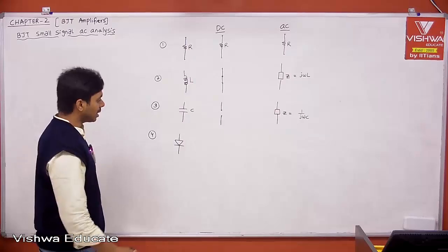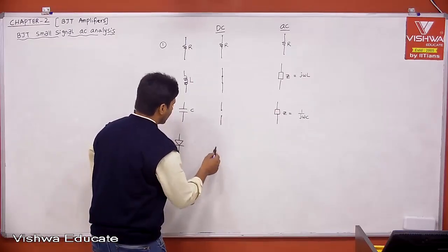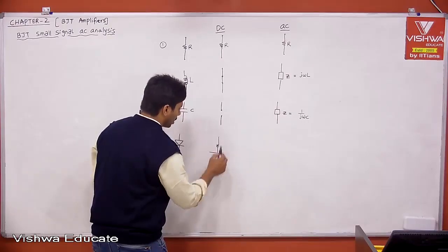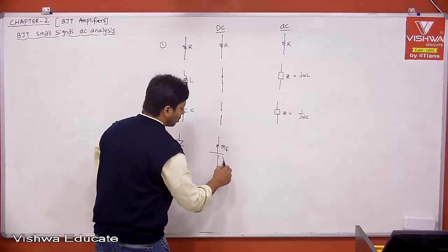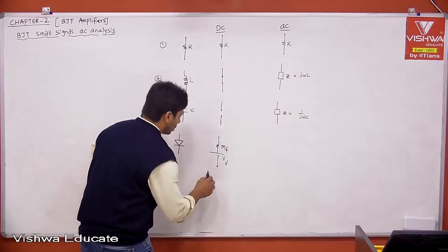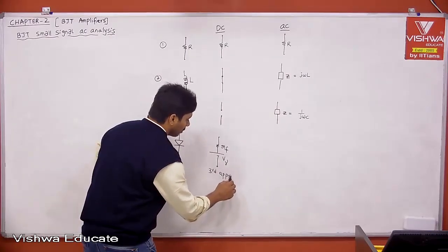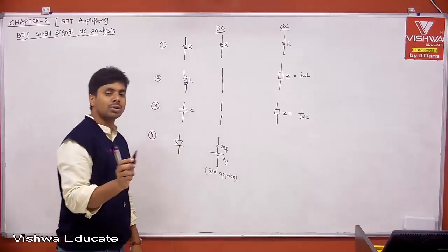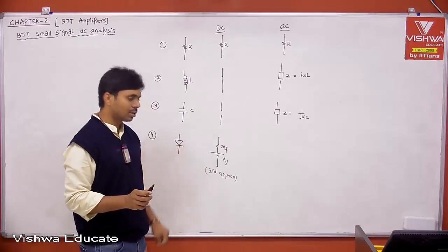Therefore, if you take the third level, that is nothing but level 3 or the practical model. Then this is nothing but a resistor and a battery. That is what I gave: the forward resistance RF, and this is our V gamma. Therefore, I am using the third approximation, because if I use the first approximation, there is no difference between DC and AC. Just to show some difference between DC and AC, I am taking the third approximation.